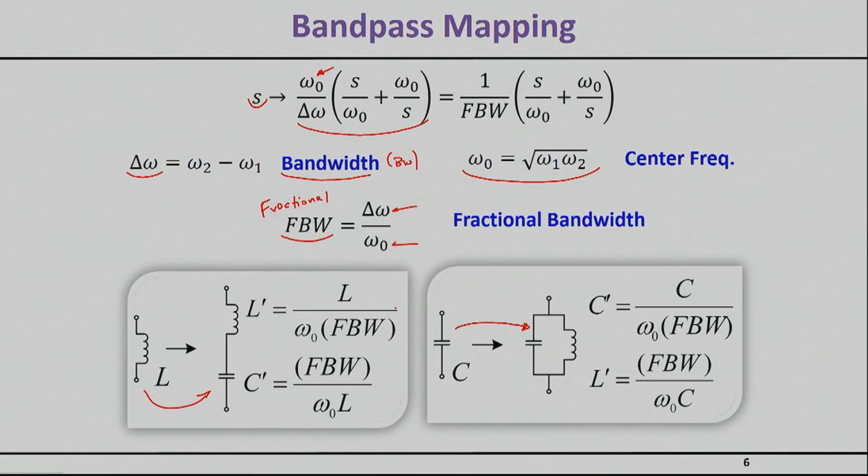Now you can see a little bit, for example, why when we were doing the synthesis with the inverters, we said that you can either choose to allow your series elements to stay, or you could have chosen to allow your shunt elements to stay. And this will have a big implication of what kind of resonator you need to implement, because perhaps your physical realization of your resonator is actually an equivalent series RLC, or it may be an equivalent shunt RLC. And we will see examples of that later on.